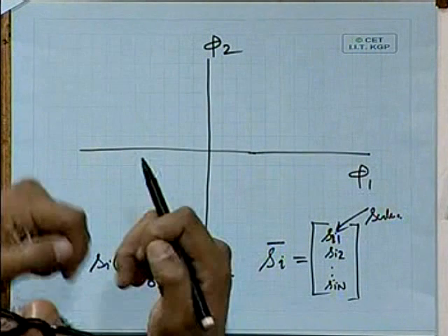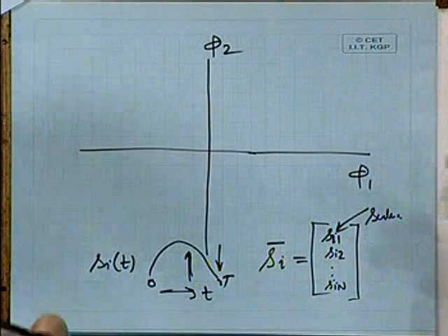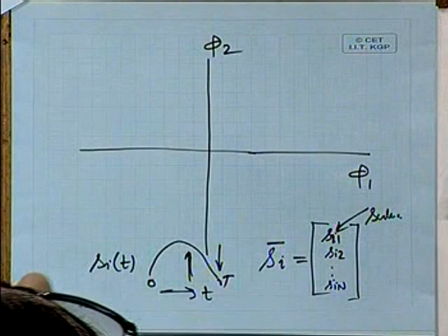If I keep on observing the noise which I may generate from any say Zener diode or resistor or any other dissipative component, you have not tried that ever really. It's very easy to generate thermal noise and see it on the CRO even. Oh yeah, okay, I'll give you a small problem later on. It's a very simple circuit; you can wire it and see that yes, noise is visible on the CRO even, and it fluctuates like it's sometimes drawn in the book.